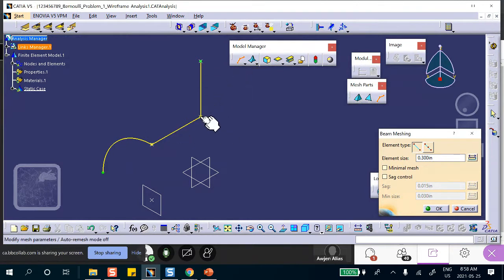Because of that, at the interface you have different nodes, one coming from the vertical piece, another coming from the horizontal piece. These nodes have different node numbers, and they don't talk to each other. So that business of connection that I was talking about, you create a connection between these two and basically say it's rigid. In other words, when one moves, the other one moves with it. But doing it this way, joining it, will avoid getting those duplicate nodes.